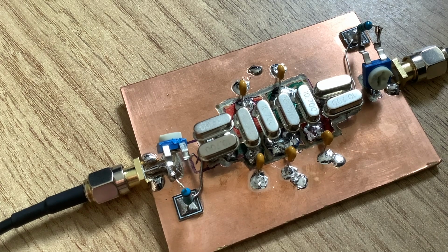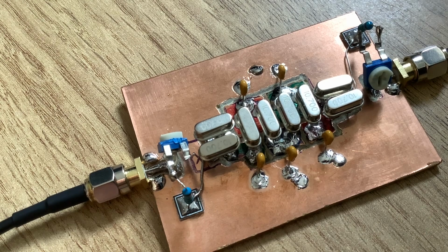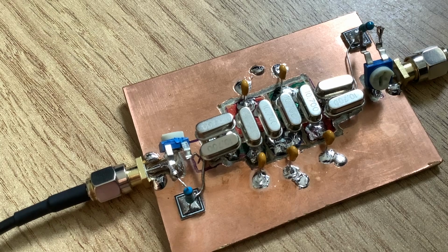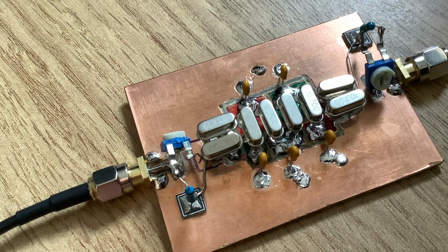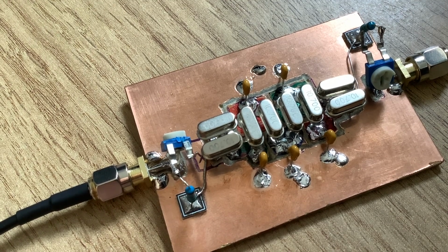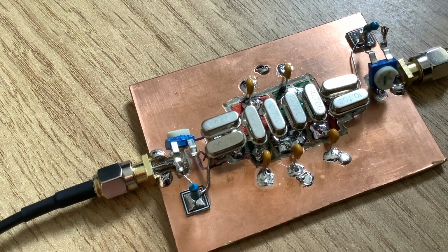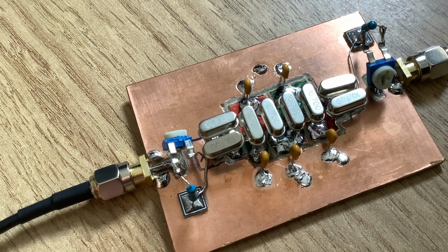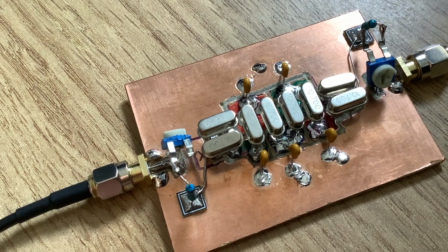So I stripped out those 270 picofarad caps and stuck in some 10 picofarad caps. And I did the exercise I'm just about to show you now. Worked out what the input and output impedance was. Built a simple little L match on the input and on the output. And it worked really well, but it was just still a little bit too narrow for my purposes. So I've started again. So now I've got 6.8 picofarad caps in. And you see what I've got here. Well, hopefully you can just about see what I've got here.